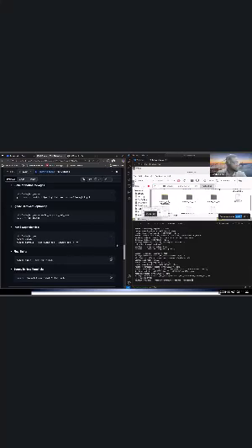All right, the next step is to cd into the mobile bots and run rosdep. So rosdep is very important. What rosdep means is you're trying to install the dependencies you need to run a particular package. So you see rosdep update, then rosdep install from path src, ignore src, -y. It's just a command to install the packages required in the src. We'll run that quickly.